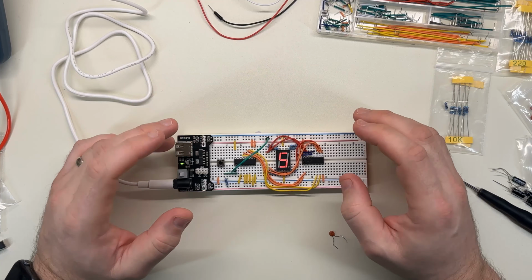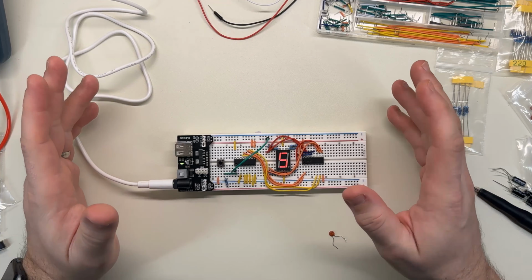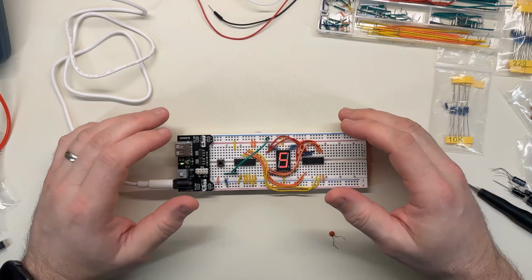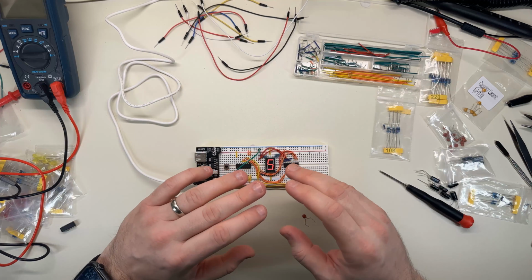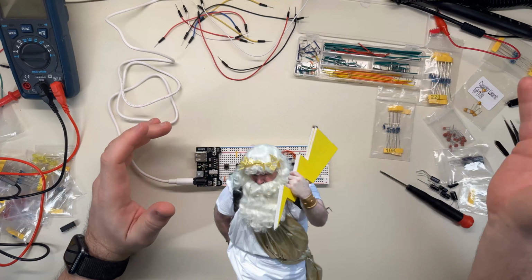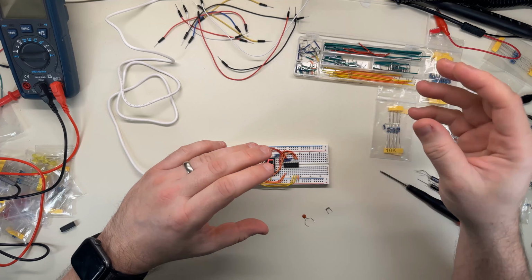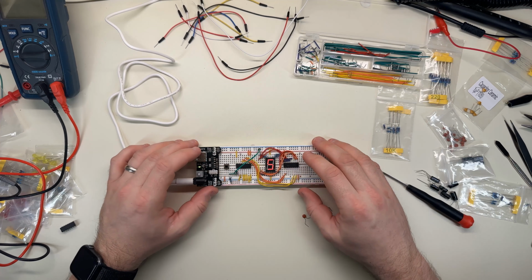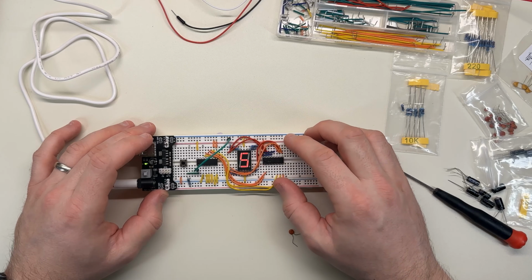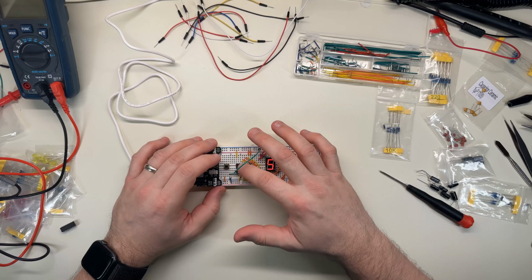Now, it also turns out there are other sources of bounce that I hadn't even considered, and I found this out after my first failure and did some more research. There are things like electromagnetic fields in the environment. A lightning strike nearby could cause an EM wave to hit your wires and create a little bit of fluctuation. It could register as a very brief signal. It can mess circuits up.